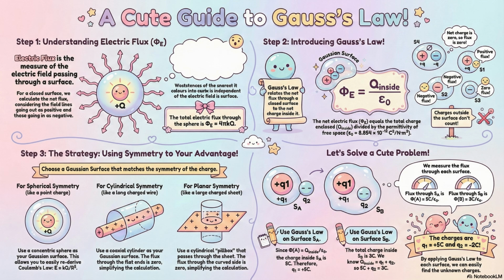Wait a second. If the dielectric is an insulator, a literal barrier that stops charges from jumping across, how does a capacitor even discharge? Where does that current come from? That's a great question because it really does seem like a contradiction. The charges never jump that gap. When you discharge a capacitor, the extra electrons that piled up on the negative plate are drawn around the external circuit. So they flow through the wires, seeking out the positive plate to neutralize the charge. Exactly. The current you see is just the movement of charge around the outside, trying to fix the imbalance. It acts like a tiny, super-fast battery that stores energy directly in a field, not with chemistry.